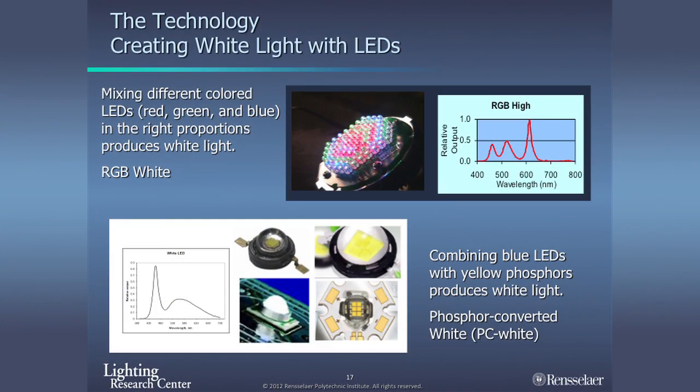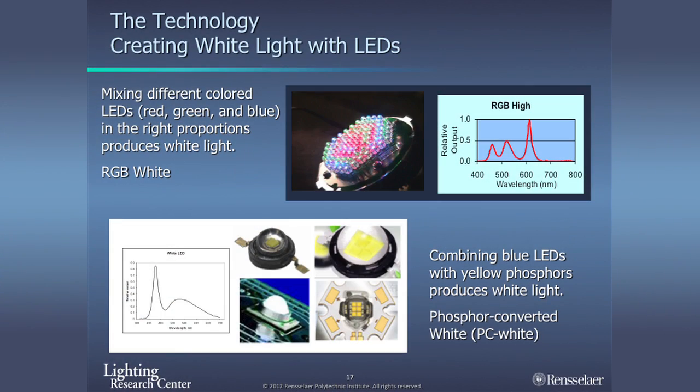Now, they can come in very, very many correlated color temperatures. So this would be analogous to incandescent light, that warm yellowish light, right up to a very, very bluish white light or above, even 6500 K or more for specialized application. Now, typically, you're not going to use this in interior. That's exterior lighting, because our eye actually is more tuned to the cooler spectrums at night. We see better under it, and so it actually gives us improved safety and efficiency to use those temperatures outside during the nighttime. For interior applications, you're certainly going to see, much like fluorescent lights, 3500 Kelvin, 4100 Kelvin.